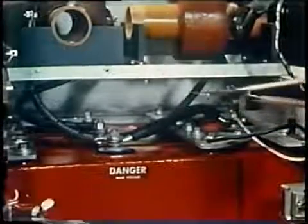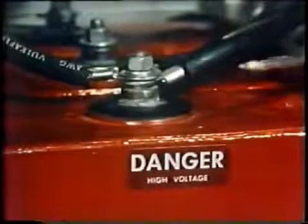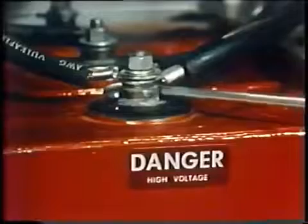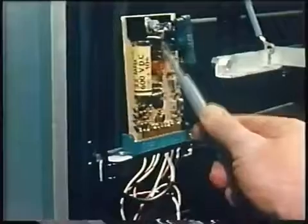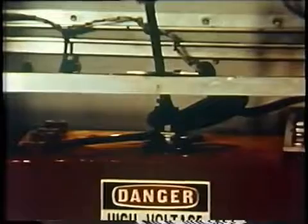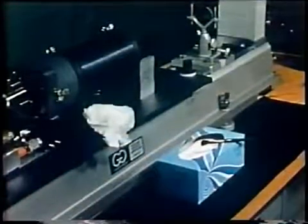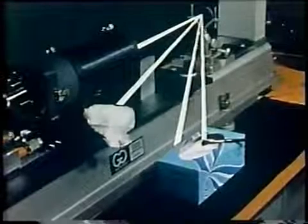Because of this danger, maintenance should be performed by two individuals, since several manual operations may have to be handled simultaneously. To make certain it is safe to work inside, all high voltage points must be grounded and remain grounded. This will dissipate any stored charge remaining in the capacitor. This demonstration shows what may happen if it remains charged. Many of the materials normally used around laser operations are flammable, and specular reflections could set them afire.